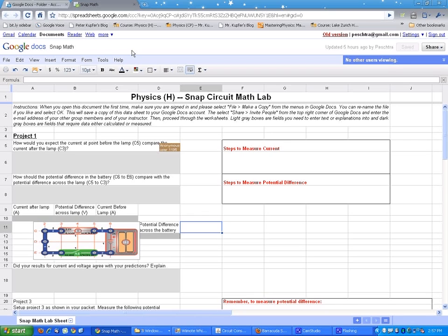Okay, if you're measuring volts, you put it in the hole with a V above it for volts. If you want to measure current, you put it in one of the current holes. Now, if you have the multimeter like Andy has, this one, the volt and the small currents are in the same hole. So you don't have to move it if you're doing that. But in the big currents, you have to move it. So that's the only difference between the two devices.